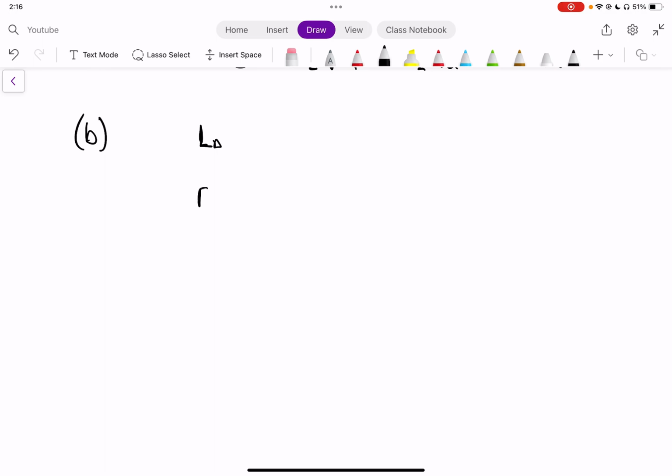So our force desired, because of the calculations and the loading that we know, is going to be equal to 5.34 kilonewtons. So in this case, our force desired is equivalent to our force equivalent, which we found in part A. Instead of 5, it's going to be 5.34 because there is an axial loading. Now, LR, or life rated, is 10 to the 6 revolutions. That's not going to change.